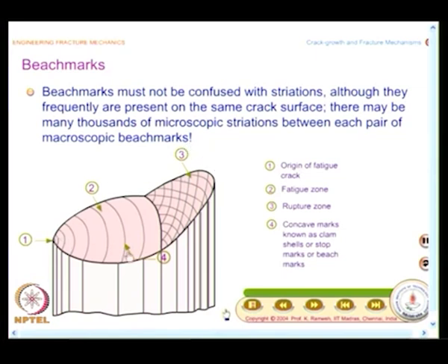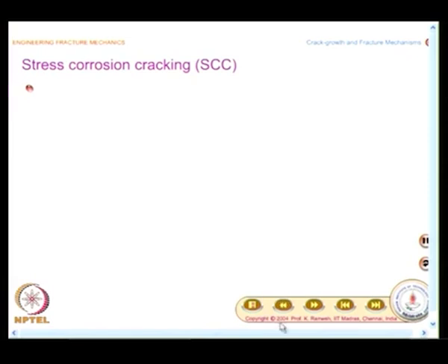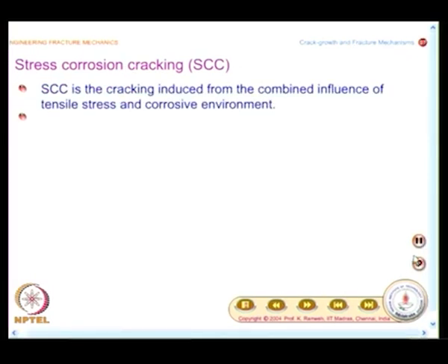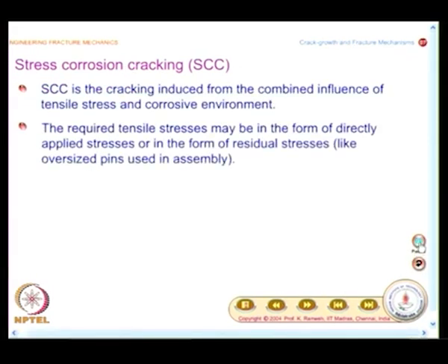And make a neat sketch of this and make a distinction between striations and beach marks. So, you will have many thousands of striations between the beach marks. So, this explains what is the mechanism of crack growth by fatigue.